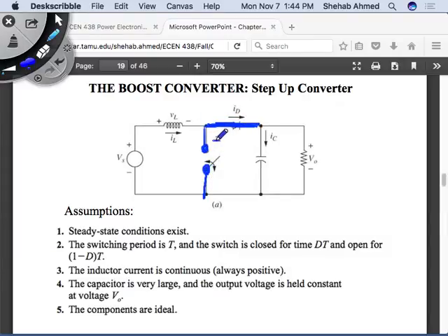So what is the voltage here? It's V out, the output voltage. How about if this is short and this is open? What's the voltage across this? V out, the same. Exact same. So in a buck converter, the switches are rated to the supply voltage. In a boost converter, the switches are rated to the output voltage.